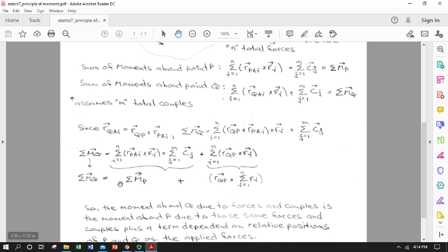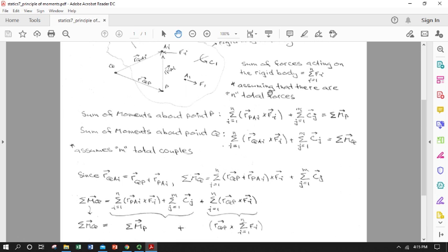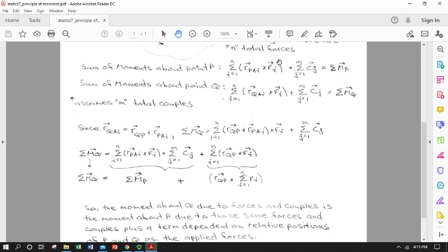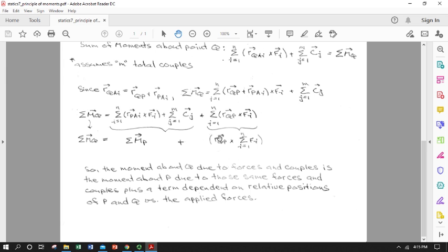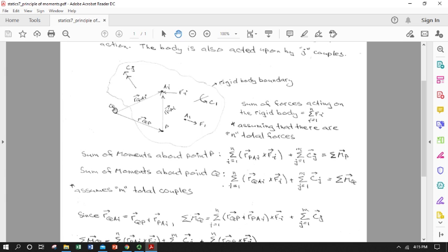So we just proved that instead of redoing all of our cross product calculations to get individual moments for applied forces about point Q, all we have to do is use what we already calculated for point P, assuming we had already calculated it, then take the sum of the forces, which we probably needed to get already if we were going to evaluate conditions of equilibrium, and calculate one cross product based on a radius vector between our 2 points of interest Q and P that we cared about.